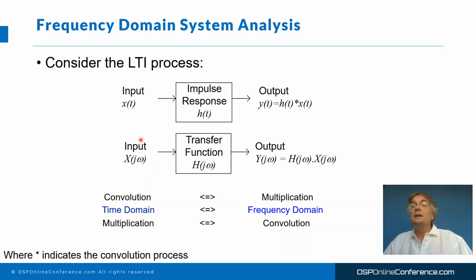We'll look at this in a minute. And then on our output, we also have to have a delay while we stream out the buffered data from our inverse FFT. So the benefit, again, is reduced MIPS. Our cost is that we have increased latency.